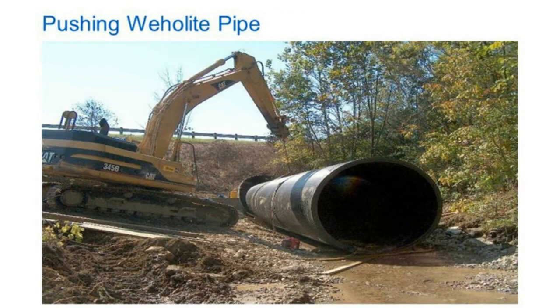So bringing the pipe up into the host pipe, there's different methods. The contractor can use a strap, which, in most cases, he's using to unload or lift the pipe and bring it into place. And just simply by lifting up on that strap, it will tighten down on itself, and then he's able to swing that arm of that excavator and actually slide that pipe right up into the host pipe.